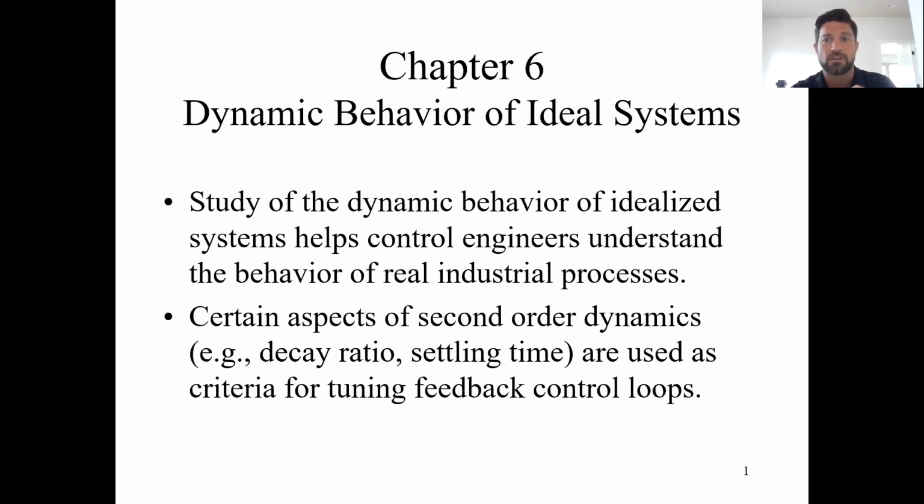Take a transfer function and predict the time-dependent response for the control variable, the final output, or look at the actual process data and come up with a transfer function that would represent that data. And the input we are always going to focus on is a step change. The step change could be to the specified flow rate or set point, something like that.